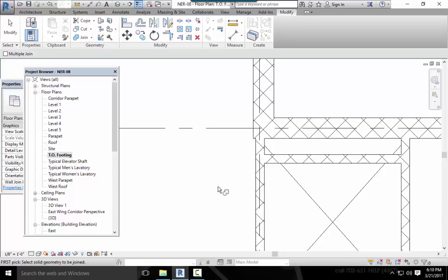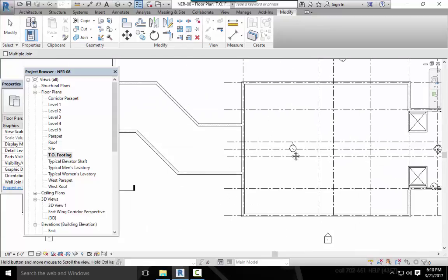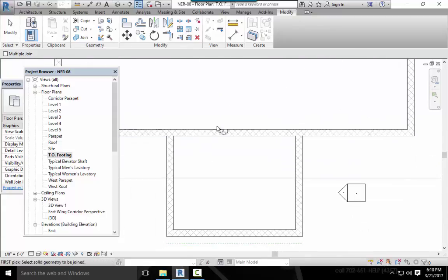Alright. Moving to the west wing, you'll need to fix one wall. You'll use the split command as follows. Zoom into the area shown in figure 8.56. That's this area over here. And you've used the split command here before, above grade. On the Modify tab, click the Split Elements button. That's this little button right here. Pick the points marked 1 and 2 and press Escape twice.